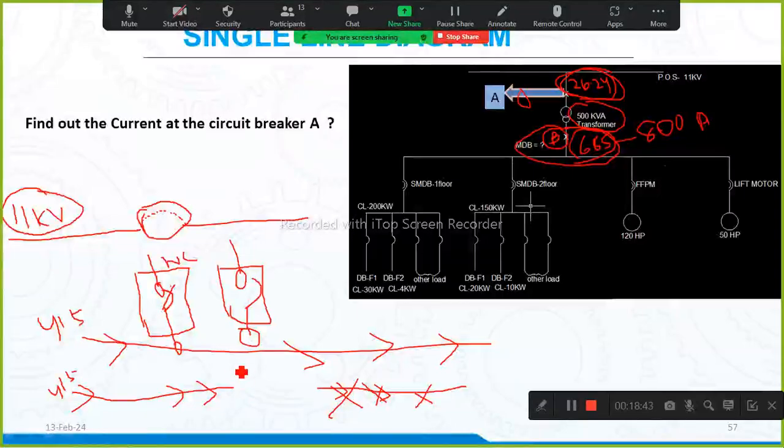Yes, sir. So when you are giving 11 kV supply, when your circuit is closed, the current flows. But when you are opening the circuit, when your circuit breaker is switching on and off, when it is moving, this total space will become an arc. Why? Because of the huge potential, even though there is no contact between them. It becomes an arc. When it becomes an arc, what happens? This MCB is plastic. The MCB doesn't have an arc quenching medium. It will become ash.